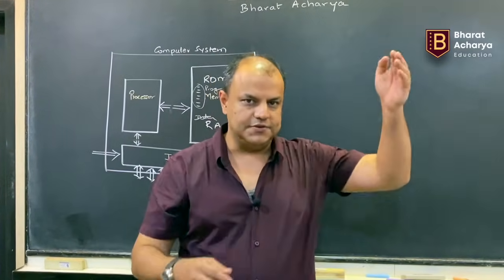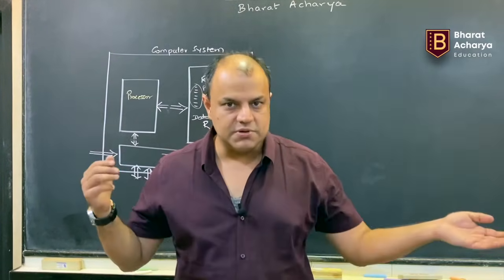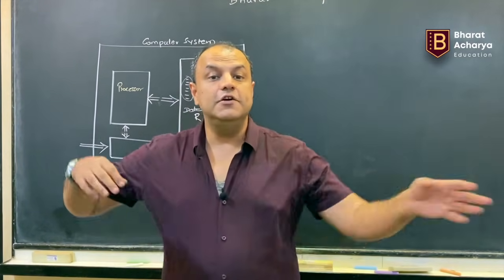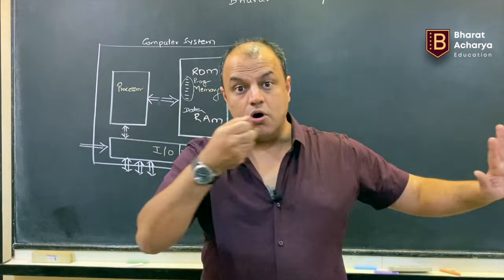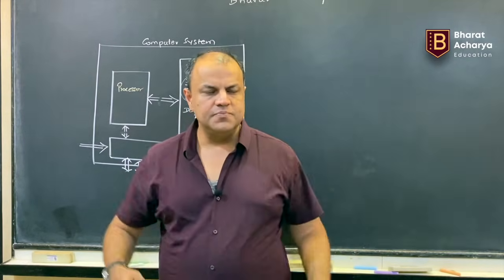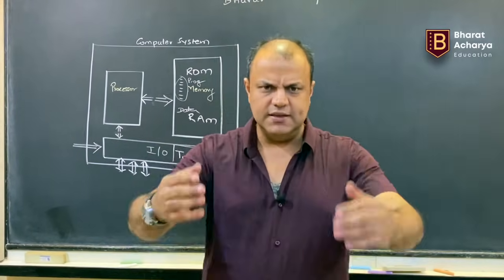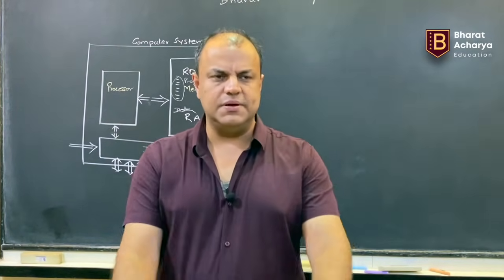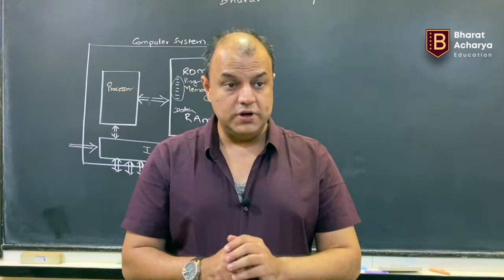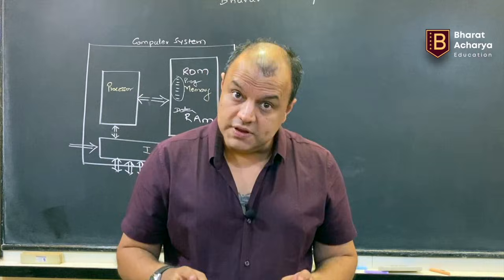The address bus gives the address at which you want to do the operation. The data bus carries the most important thing, the data that you want to transfer. And the control bus decides whether the data will be sent or taken, which in technical terms is called a read when the processor takes the data, and a write when the processor sends the data. These things you will learn in detail as the subject proceeds ahead. Anyway, you'll need all these components connected with all of these buses.